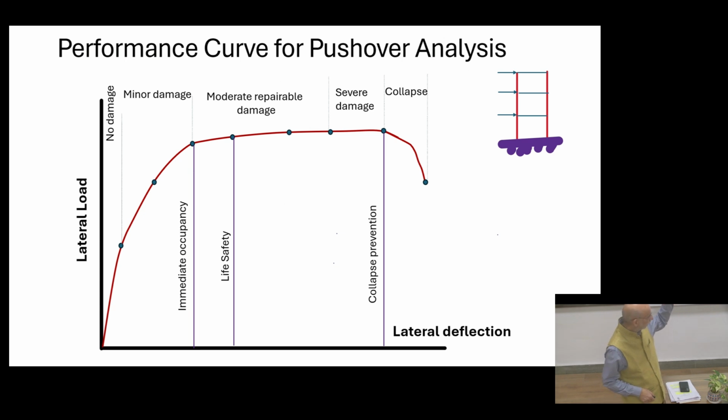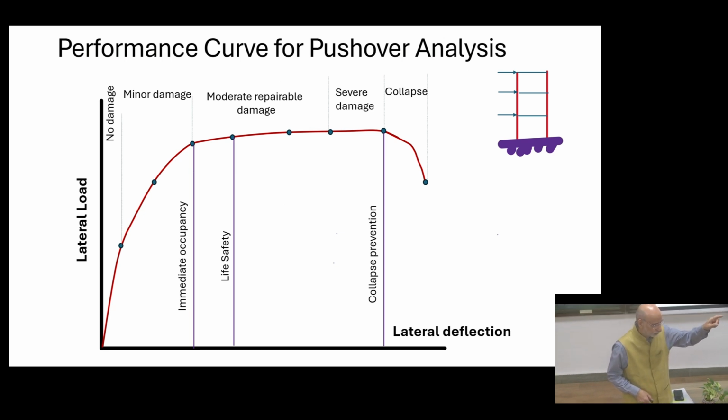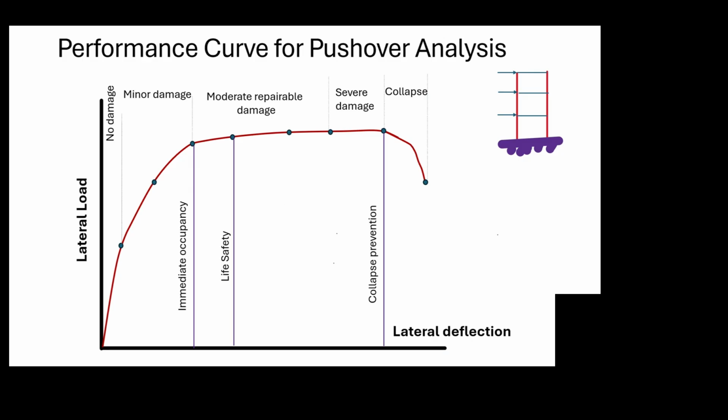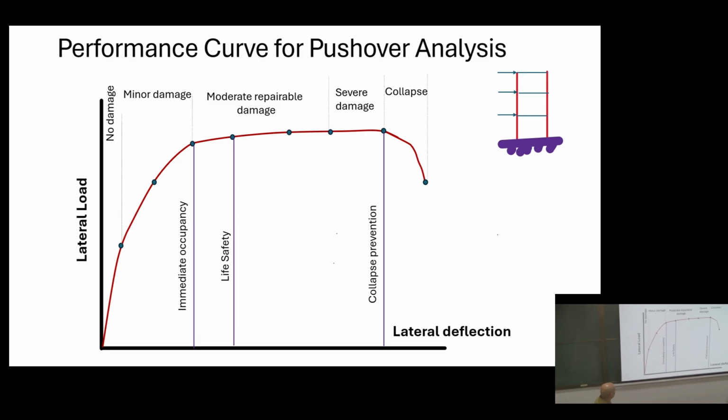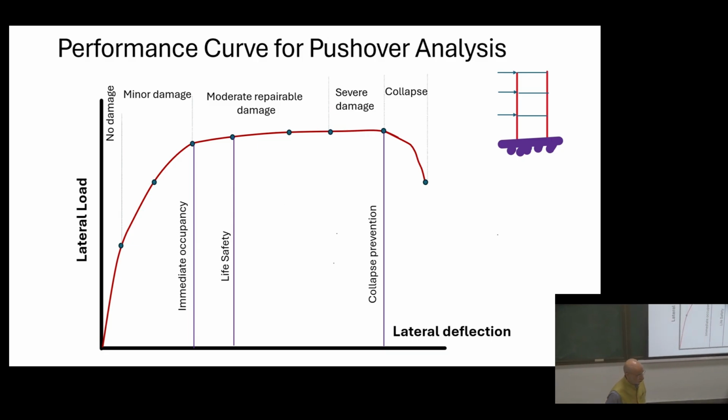If you can recall the earlier slide which I showed you, how much minor service damage is acceptable, and how much damage until collapse. All those levels can be measured precisely. If in this area, only minor damage will take place, that means non-structural damage is going to take place. When you go beyond, there is still reserve strength, approximately of the order of 15%.